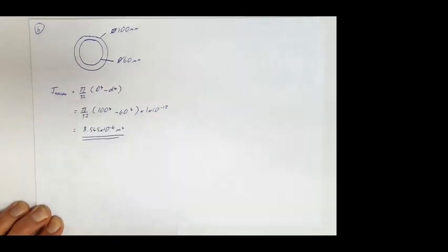Okay, now the J value before was 9.82 times 10 to the minus 6. It's now gone down to 8.5 times 10 to the minus 6. So it is going to twist more, but it's going to be a lot lighter because we've removed that material.